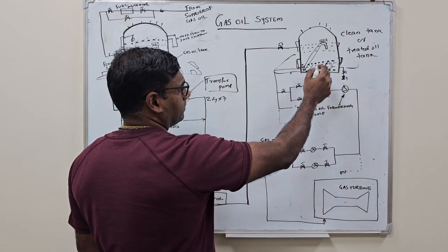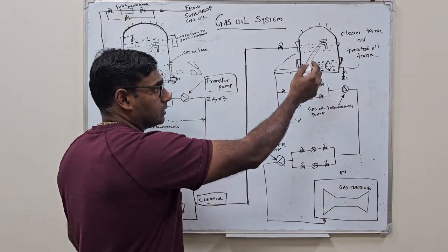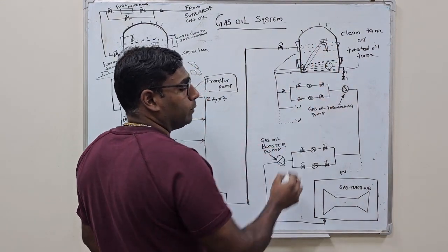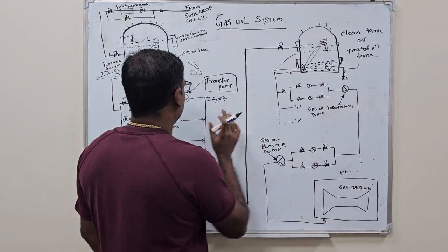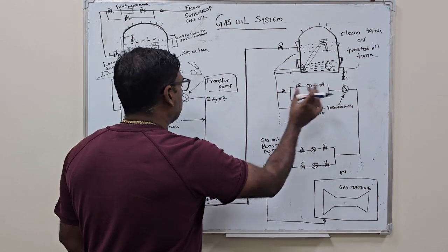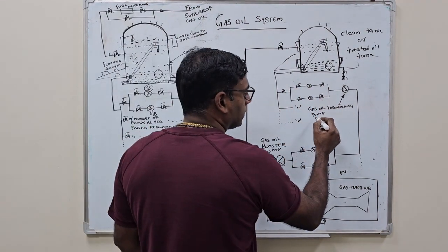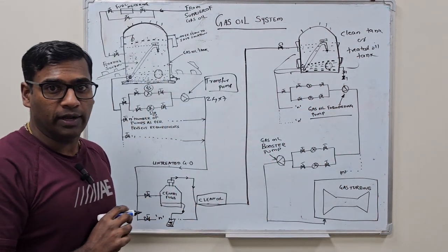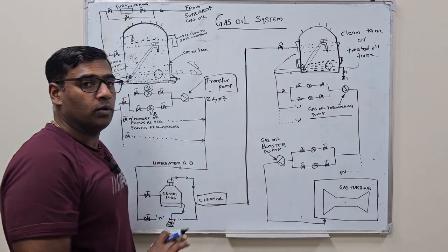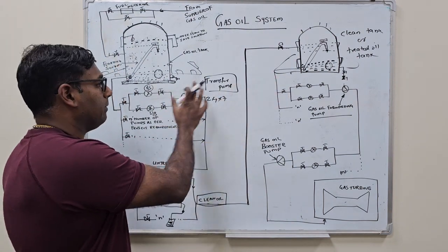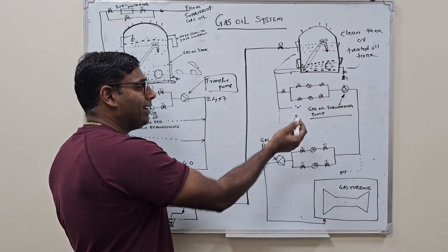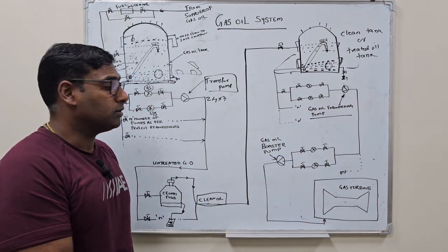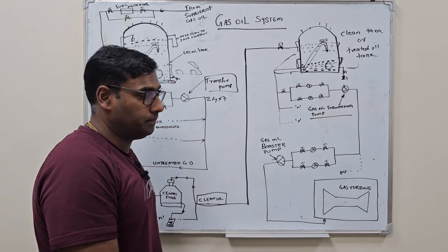Coming back to the system, from this floating section, oil will be sucked in and it will go to pumps. They will be almost similar to these transfer pumps. These pumps are normally called gas oil forwarding pumps. This could also be a centrifugal pump with the same kind of filter ports and filter mechanism over here, and it could be n number of pumps based upon the requirements.